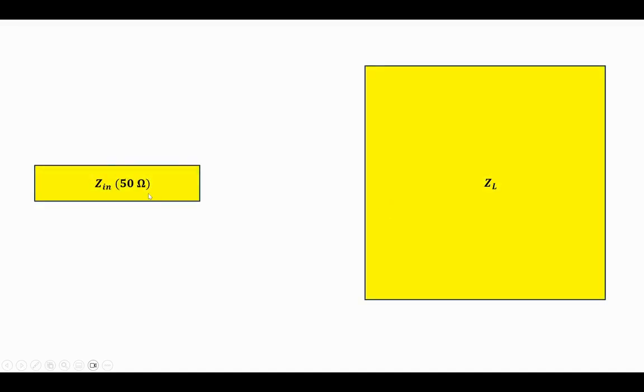We have our transmission line, the feed, which is at 50 ohm, and we consider the load to be the patch antenna, the patch itself. So we want to include in the middle a quarter wave impedance transformer of length lambda over 4 times the square root of the effective permittivity.